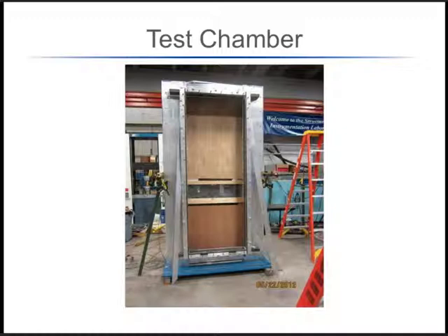So you can see the base. Then our piece of glass is put in there. It's retained by the frame that's around it. It's got rubber gaskets inboard and outboard and typical setting blocks like you'd have in a normal curtain wall or window setting. And we actually tested the glass to failure.